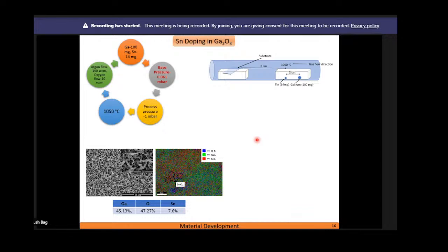Doping, again, you know that typically in any material, you'll find 10 to the power 22 atoms per centimeter cube, and dopant atoms should be 10 to the power 17 or 18. But alloyed means there are almost equal portions of atoms. So alloying is not doping, in case of electronic application, obviously.